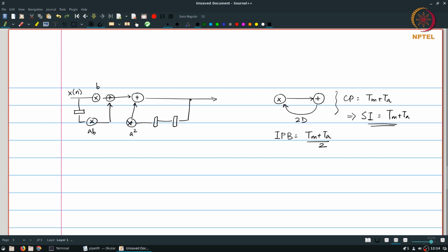As before, there are 2 things we can do over here. One is, if the multiplier and the adder have more or less equal delays, then we could just use a pipelining transformation over here. And yes, this is perfectly legitimate and would work fine to reduce the time taken inside the filter, or in other words, to increase the throughput of the filter.